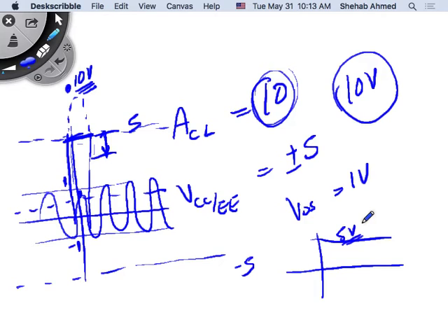And I don't want to amplify the effect of my bias current. I have a 1 volt offset voltage, okay, that I'm not able to deal with. The best I can do is let it pass through as an offset voltage. So I will have 1 volt here that I lost, but I still see my signal. I cannot amplify my signal as much as I wanted to because I'm losing some because of the offset voltage, right? The offset voltage is there, it passed through, but it's not being amplified. But at least it's passing through as an offset voltage without magnification, but my signal is being magnified.